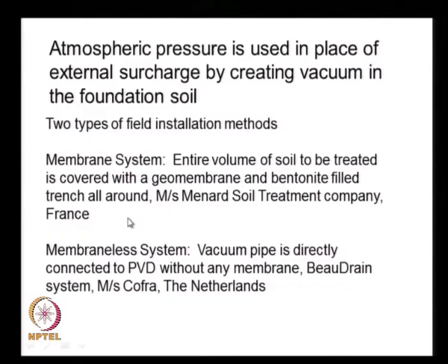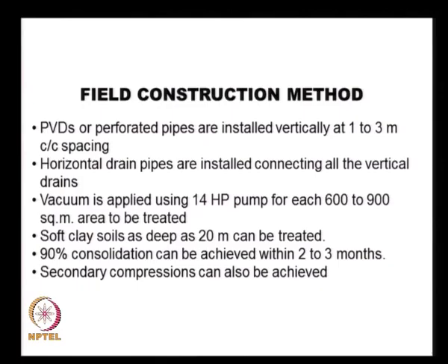And there is another system called the membraneless system, wherein the vacuum pipes are directly connected to the PVDs without any membrane, and this is called the Beau-Drain method that was developed in the Netherlands. The membraneless system is suitable for sites where we have a thin layer of hard clay that is relatively impermeable, and it will not allow the vacuum to leak. And both of them can be illustrated. I will show you the pictures later.